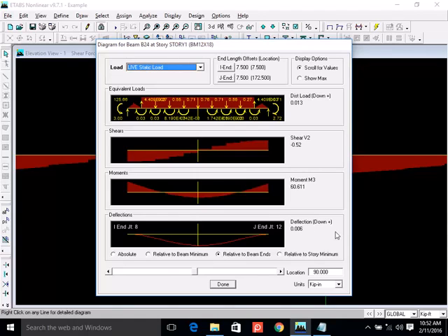The way we design it is that we don't want deflection for dead loads. That's why when the beam is constructed, we prefer to have a camber in the beam. So the dead loads neutralize the camber, and the live loads have positive deflection, I mean downward deflection. So the deflection is generally checked for live load.